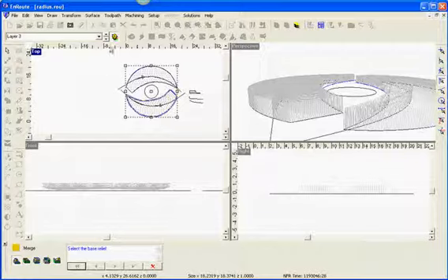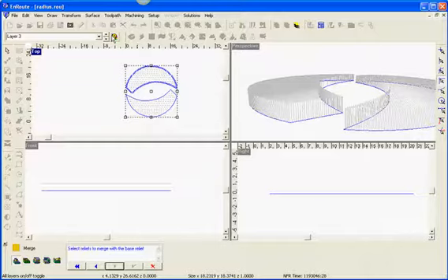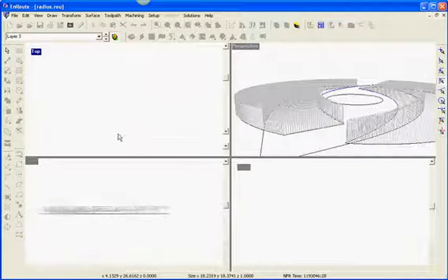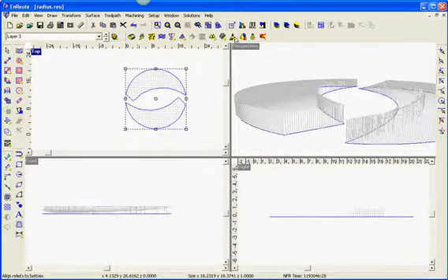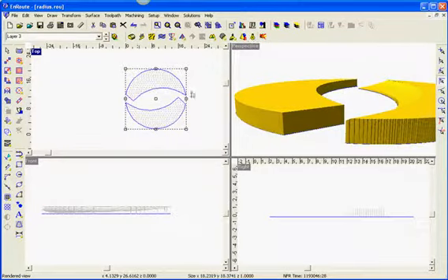Let's try this one more time. Select the base relief, do the top one. What relief am I going to add to it? I'm going to select this internal component here. And I'm going to say merge lowest. So since this new thing I created is lower than the other one, it should result in me taking away that part because it's lower than what was already there.